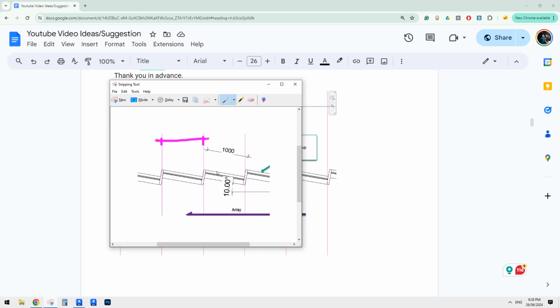Okay, width, and then we're going to model this as part of the curtain wall panel. And also, actually, we are going to model everything inside of this panel. So this is a glazing, right? And then also this mullion, both the top and the bottom mullion, and this will be one of the curtain wall panel.